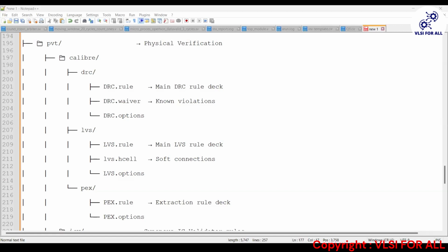So you understand, right? The PDK file structure is very important. In the PDK file structure, we have the models folder, the cells folder, the tech file, the LVS file, and the Cadence file, let's say. In the models folder, we simply have the SPICE files. In the cells folder, we have the .lib files, .lef files, .gds files.